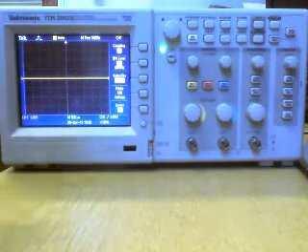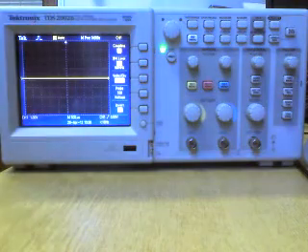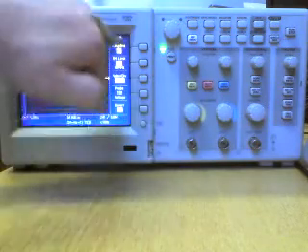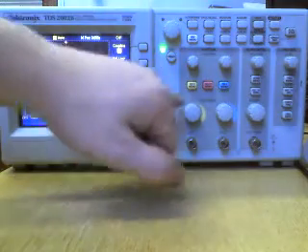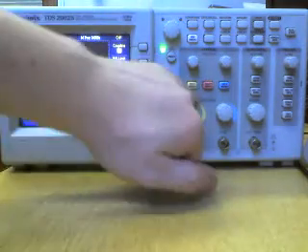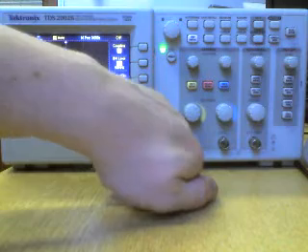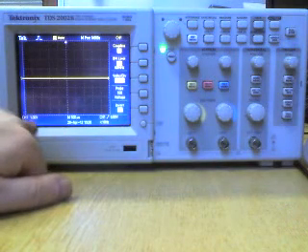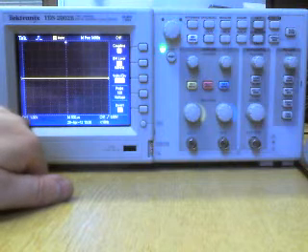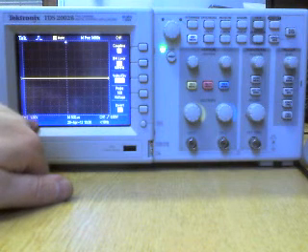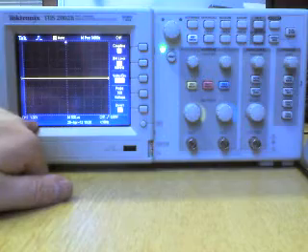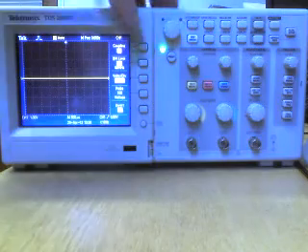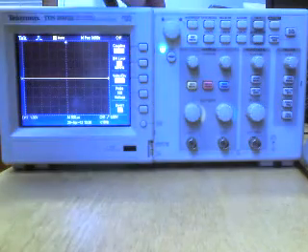Right then, on the oscilloscope screen, if we go to channel 1, it displays our channel 1 settings. Okay, volts per division knob. There's no numbers around our volts per division anymore. That's because it's actually on a menu on the front display. Down in the corner here we have channel 1, and our volts at the moment is set to 1 volt per division. Our coupling is set to at the moment DC, so you might want to change that to ground.